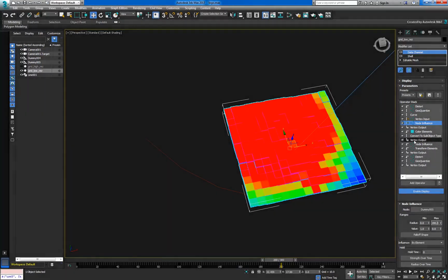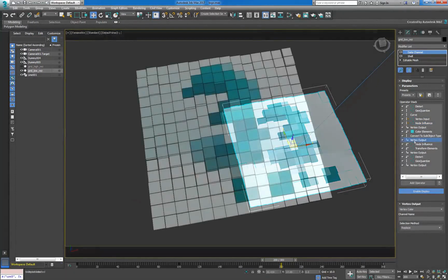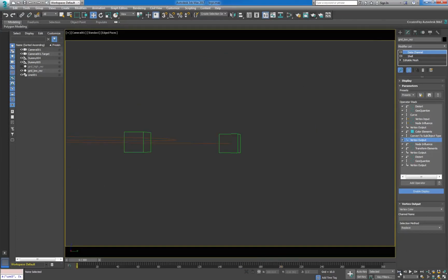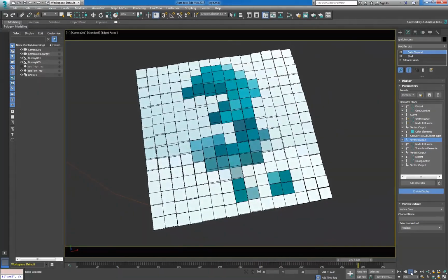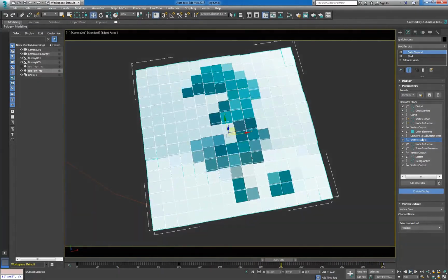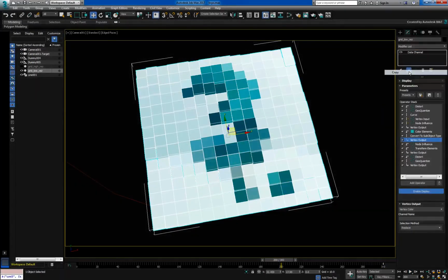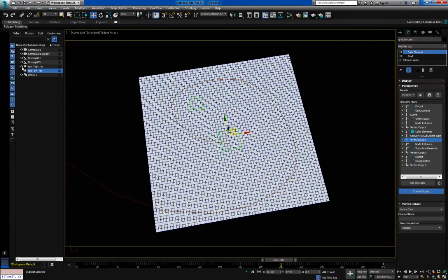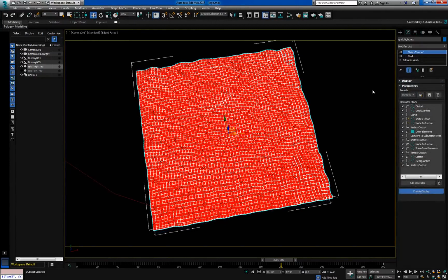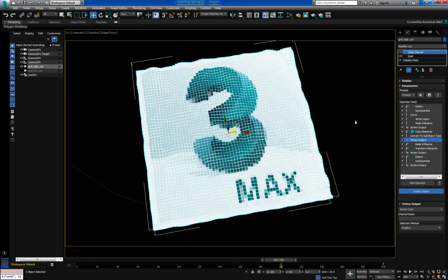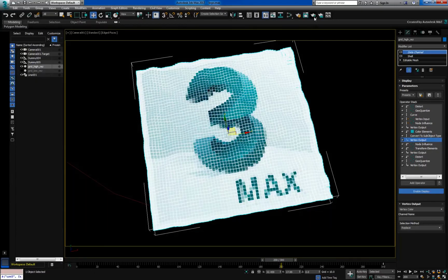To get a nice preview of our animation, select the following output operator. The final step is to copy the data channel modifier onto the high-resolution grid. Paste it as an instance. At this point, playback might slow down because of the number of operations performed on each vertex, but our final result is ready to view. We're now ready to sit back and hit render.